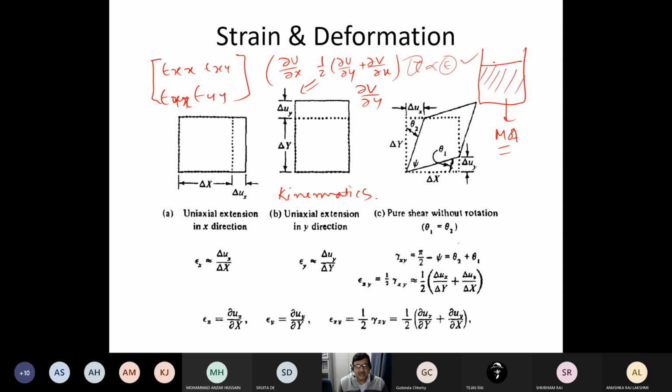Without using any law, Newton's law, Hooke's law, anything, just taking rectangles and looking at their movements and creating situations, I can go for a kinematic analysis to get the components. When you have displacement, it will be Hooke's law. When you have this, strain will become strain rate. I will immediately show you strain will become strain rate. That will become Newton's law of viscosity. One minute.